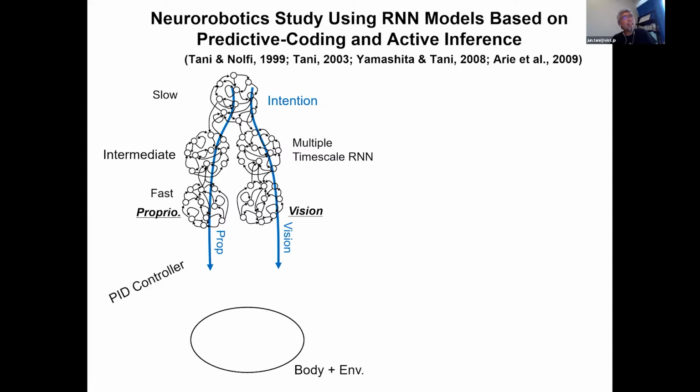In the case of a robot, that is predicting the next target joint angle, which is fed into the PID controller, and motor torque is generated, actually acting on the environment. Then we have a state change in the environment, and proprioception and vision come in. So we have a prediction and the reality comes, and then we have some kind of error.